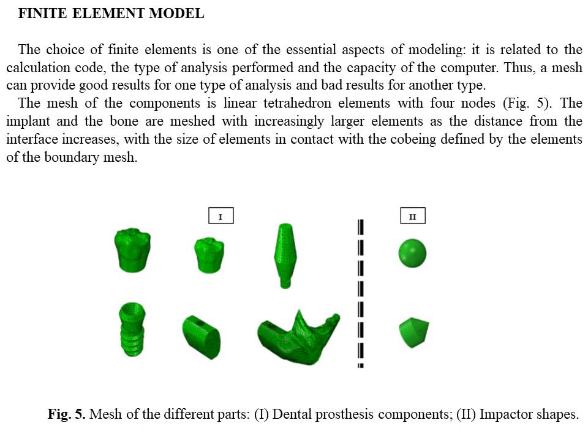Finite element method. The mesh, the choice of finite element is one of the essential aspects of modeling. It is related to the calculation code, the type of analysis performed, and the capacity of the computer. This mesh can provide good results for one type of analysis and bad results for another type.